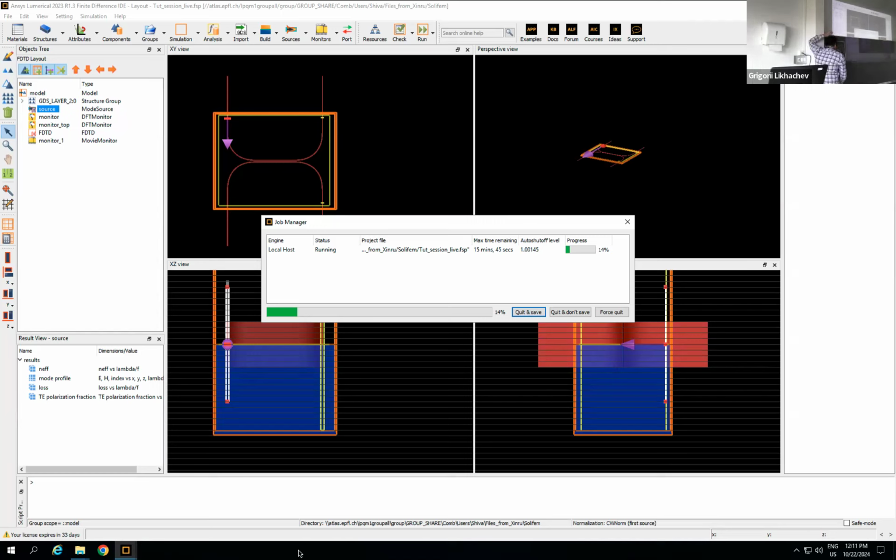And at that time, what you need to do is add a rectangle. You need to add a rectangle slab with that much thickness, like 300 nanometer or something, and then choose the property for that material. You would choose SiO2 as the property for this material, and then choose background as air. No, you won't have two different backgrounds. You would have air as your background and your rectangle slab as your SiO2.